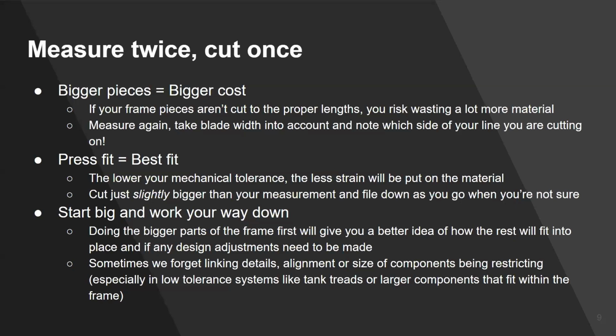And another thing that I was taught a little bit later was note the side of your line. A lot of us use Sharpies, and that's a very thick line. And that thick line, depending on if you're cutting straight in the middle, straight to the side, or whatever side of it you're cutting on, can make a huge difference in how things are going to fit, especially if they need to be perfectly fit to each other or aligned with each other. So note which side of the line you measured from and which side you should be cutting on, where you should be aligning the blade of your saw. That will give you the best final product. It'll be the cleanest one.